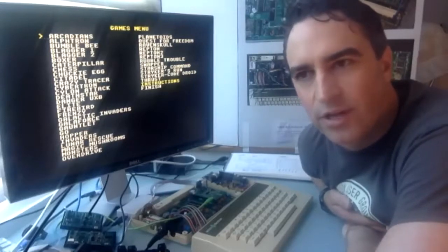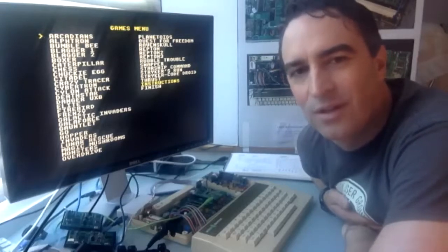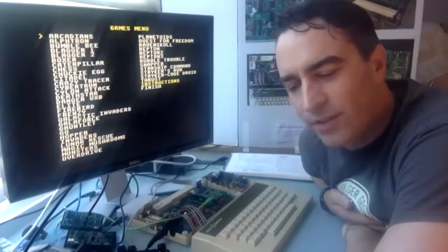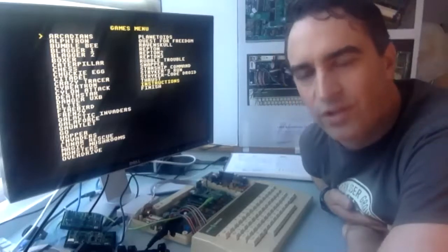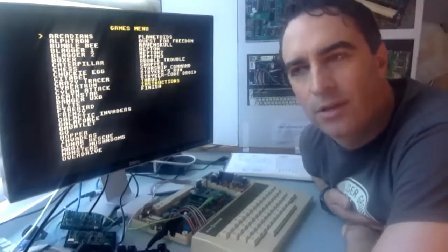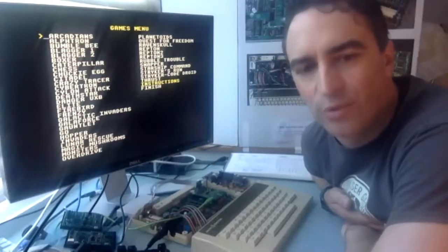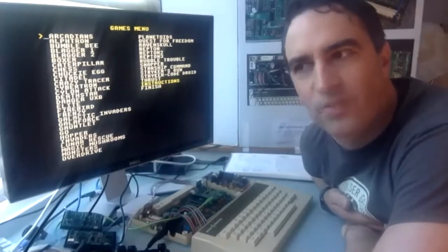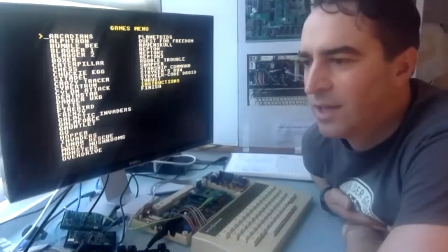It looks like it doesn't support entities right now in VHDL, which is pretty fundamental. I think basically you can have a Verilog design which pulls in self-contained VHDL modules, and Icarus will test them just fine. But you can't have a VHDL module that pulls in another module, which this project does all over the place. So yeah, let's see what I can do there.